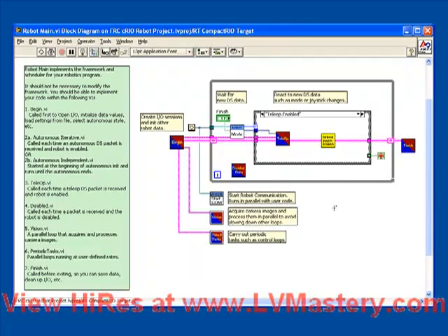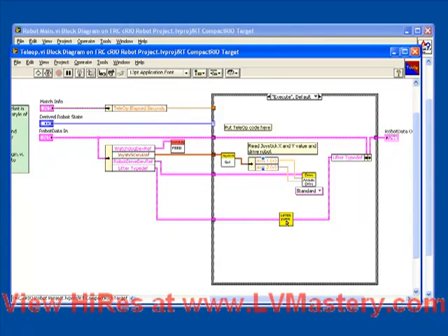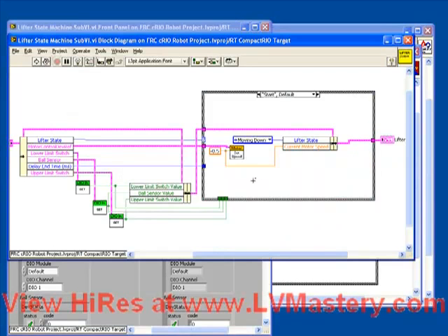So let's review what the problem is. This particular code we created, if you remember how it works, is a state machine which essentially automates a lifting mechanism. The mechanism moves down to the bottom and waits for a ball to come into the field of a sensor. As soon as that's read, there's a delay, after which point the lifter goes up until it hits a limit switch. When it hits the upper limit switch, it immediately comes down until it hits the lower limit switch, then it goes back into waiting for a ball.